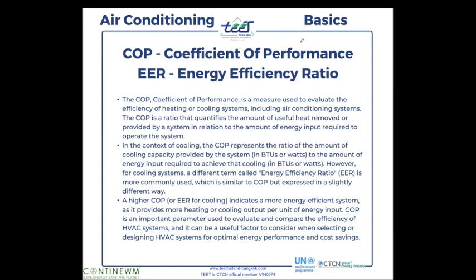And with energy, you can compare energy. You can compare kilowatt hour and kilowatt hour, okay? Whether they are electrical energy or heat energy, you can measure in the same units, okay? If the electrical energy that you consume, that you pay for, is smaller than the heat energy that you remove, the coefficient of performance will be high, okay? Because the smaller the energy you use to remove the higher thermal energy, that's better. So the higher the COP, the better, okay?